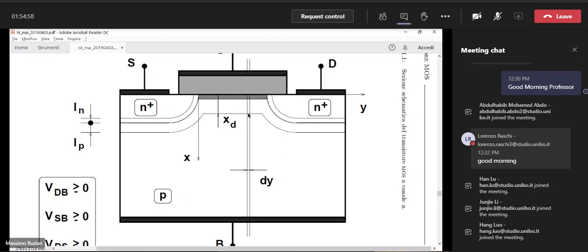The ASCE approximation, you remember, means abrupt space charge edge. That means that we go from a fully depleted region, a region in which the only contribution to the charge density is due to the dopant, to the neutral region with a discontinuity here, okay?